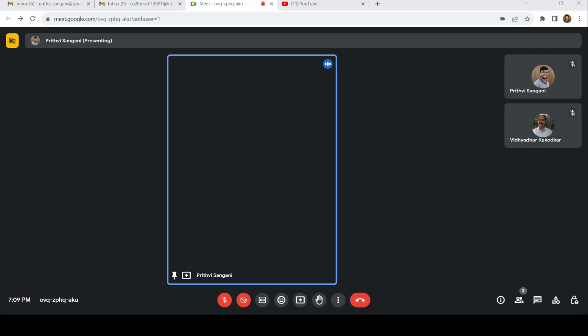Now, what is the compatibility condition? Compatibility condition says that delta 1 plus delta 2 is 0. So with this we can say minus 54.14 plus FBE times 4 plus 4 root 2 equals 0. Again we have taken A as constant. If A is changing, then you need to include that in the summation part, so in that case you will have Ai also. But in this question we have taken A as constant.